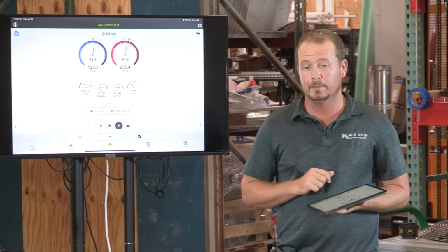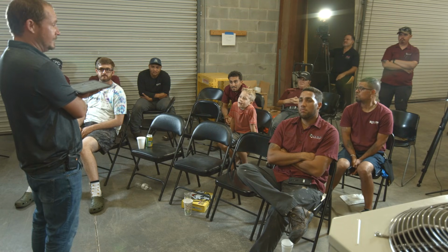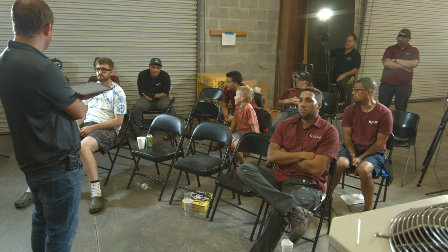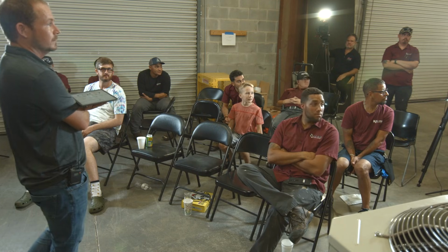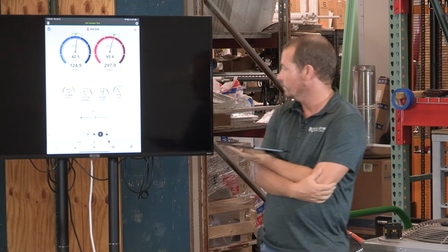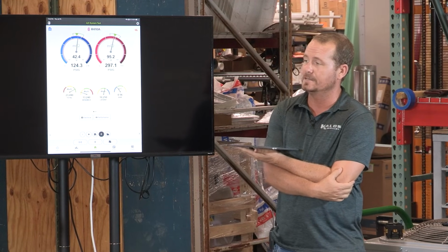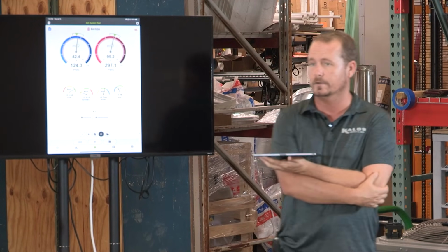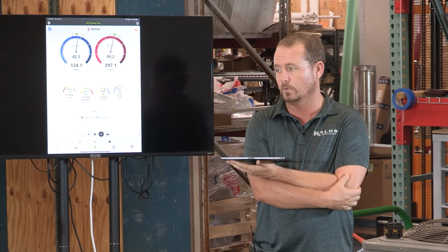All right, that's basically all I wanted to show you. Any questions about that? Anything to add? I want to get it to 2. It won't go to 2. Let's take a piece of flex and do some supplying. Usually the motor will limit itself. The reason it's not is because this is a constant torque motor, and so it is ramping up in order to compensate for the poor airflow.